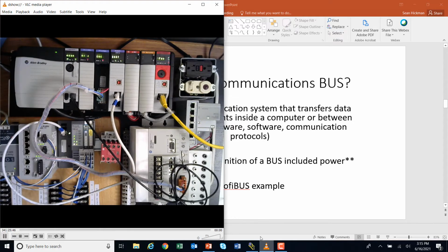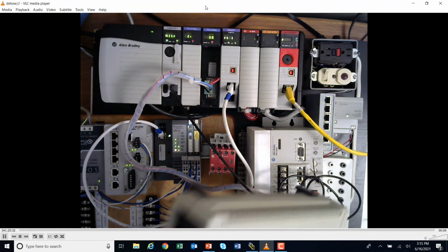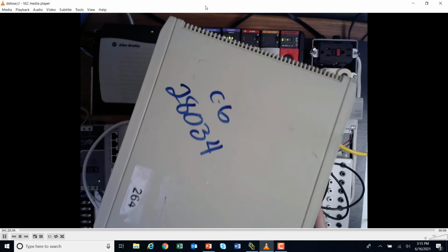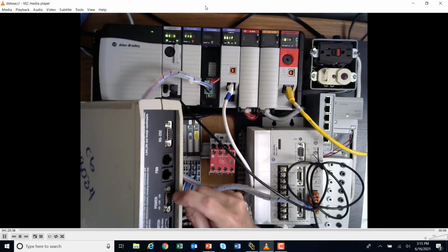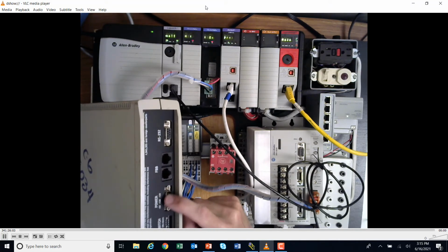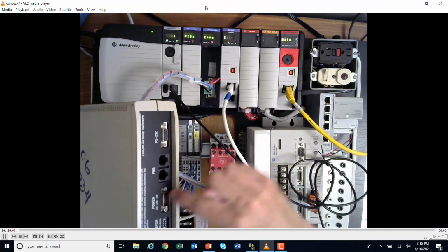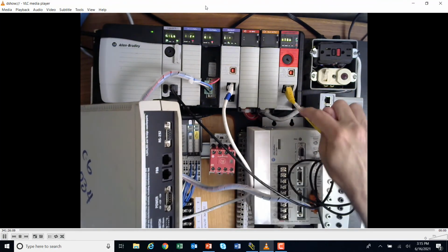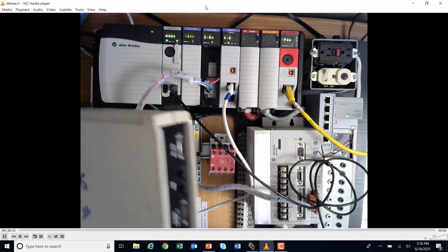And so what I've got right here, if I make this large again, I've got a sensor right here. This item right here is a 3D magnetic sensor array. It's very cool. But the issue with it is it's got a 9-pin RS-232, a DB9 port right here. Well, that is not an Ethernet port. I cannot just plug this into here, even though I would want to. So this is going to push out information, ones and zeros, I guess you want to think about it, and I need to convert it.